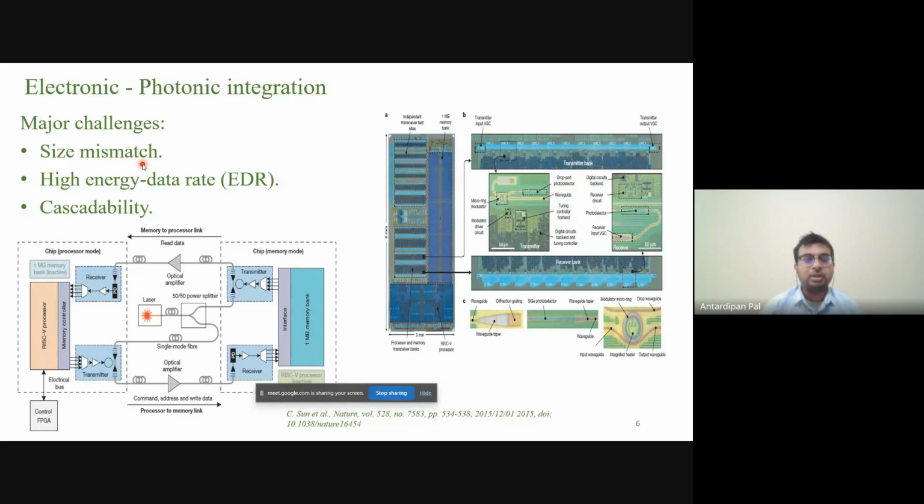What is 5 nanometer? I don't know. Because now the problem is what TSMC claims to be 3 nanometer, a certain dimension. What dimension? It can be metal 1 pitch, it can be the gate pitch, whatever, but never the gate length. So TSMC claims, say, suppose 3 nanometer to be a certain dimension. It's never true that Samsung will claim the same dimension to be 5 nanometer or 3 nanometer. They use some different measuring strategies.